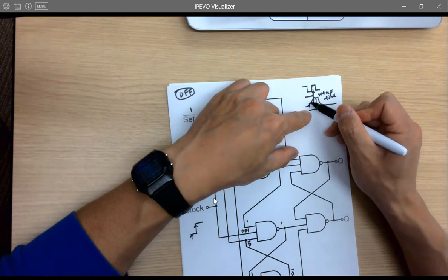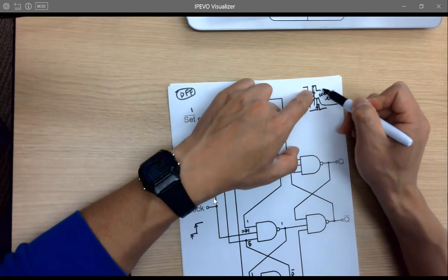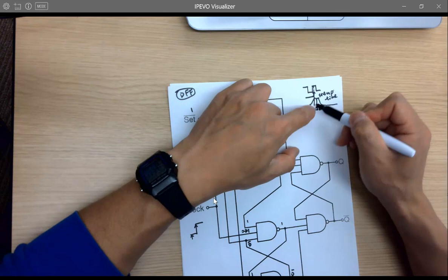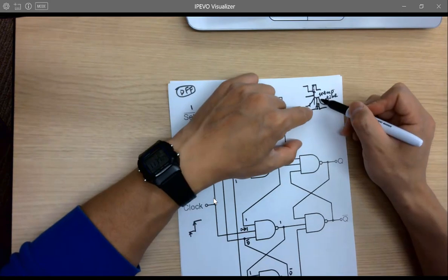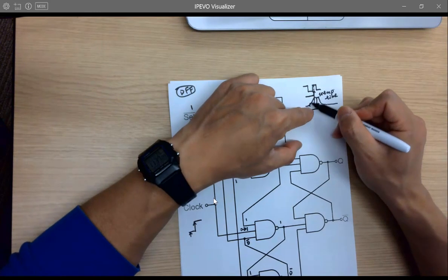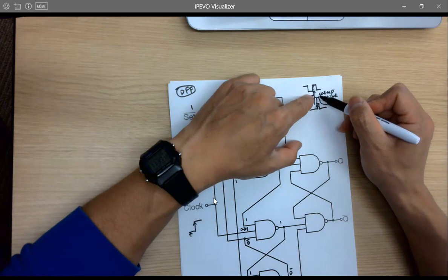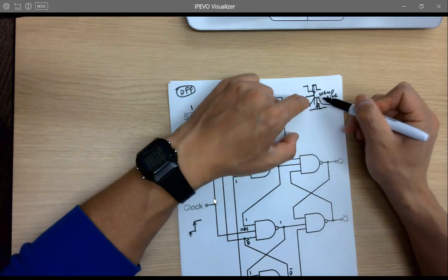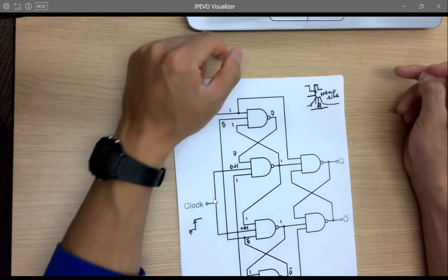You don't want to sample anywhere else. So for the ideal digital signals, it's easier, but for the real world signal, it just looks different than this one. It's just super fast and the rising edge and falling edge are comparable to the period or the on time or the full time. You need to sample exactly in the middle to get accurate data.